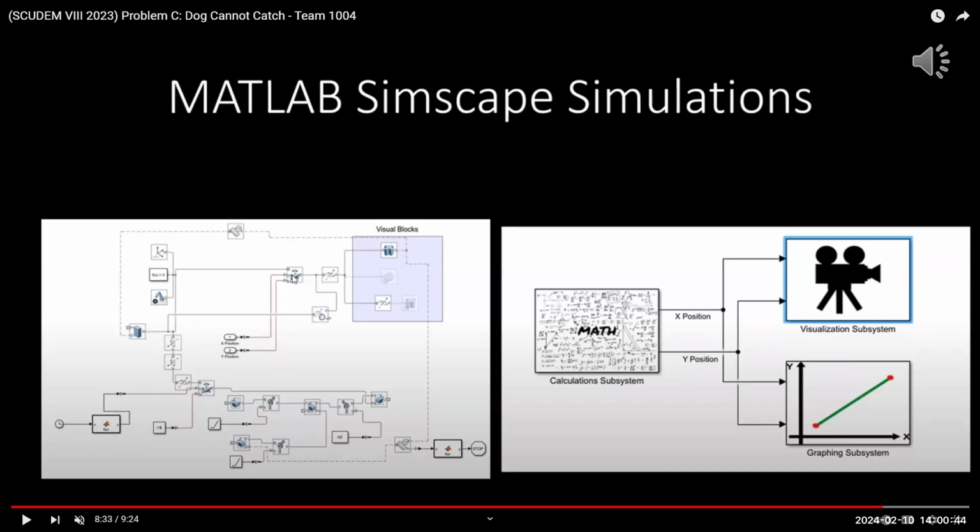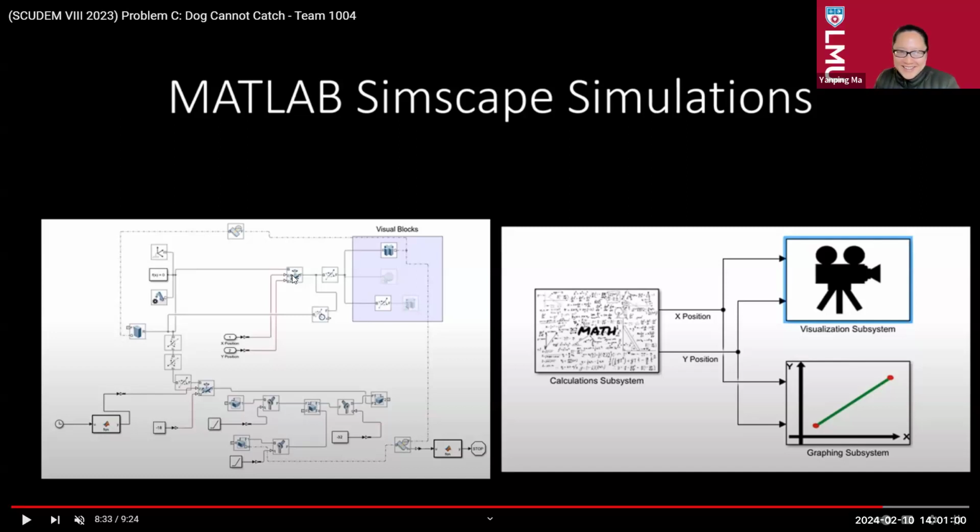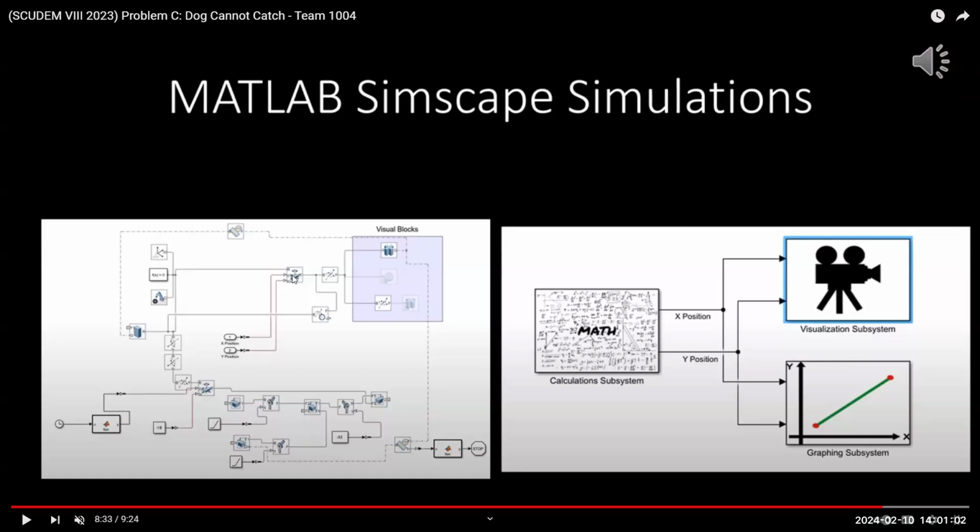Otherwise, there's plenty of things you can do when you're actually running the simulation to reduce runtime. Most commonly, we'll have runtime issues, and they are kind of out of the blue. Your model is either very fast when it runs or very, very slow when it runs. And generally, the slowness is because you added in certain springs and they behave just perfectly enough that it takes hours to run a simulation. And then you can reduce the K value and it takes minutes. So it's kind of playing around with it to see what you need.